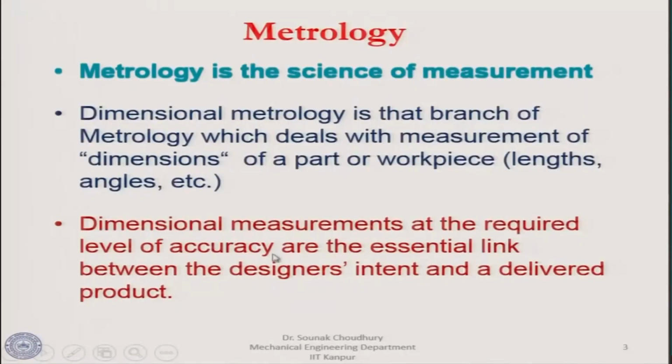So, therefore, what it is telling here is that measurement is the essential link between the designer's intent, what he wants to do, and the delivered product, because the delivered product has to exactly match with the intention of the designer, and the intention of the designer is laid down on the drawing, through the dimensions, through the tolerances, through the fits, all those things we will be discussing now.